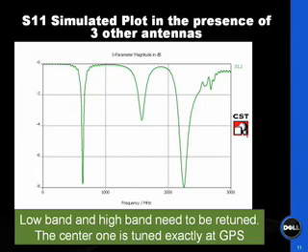Then you have to assign the boundary conditions for each component. When we calculated this for a WWAN diversity, which also has a GPS antenna, it came pretty close, but of course it needs some retuning in both the lower and the higher band. And in the GPS it was perfectly tuned at 1575.